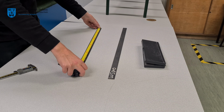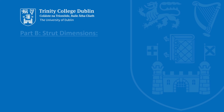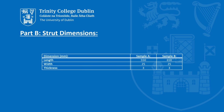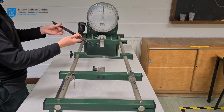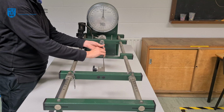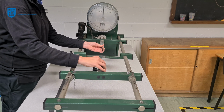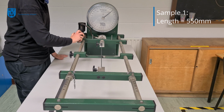We will test two different struts with different overall lengths. Their dimensions are as follows. This rig uses fixed supports at both ends. The struts are placed between the supports and locked into place. Force is then applied to the specimen via the hydraulic jack.